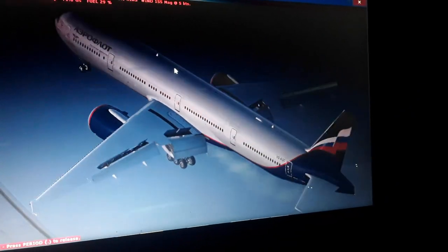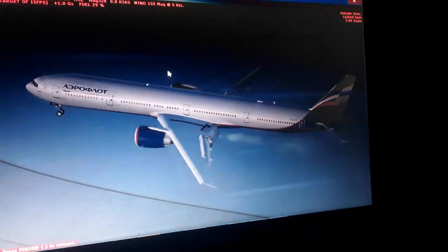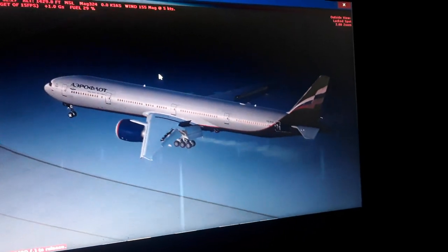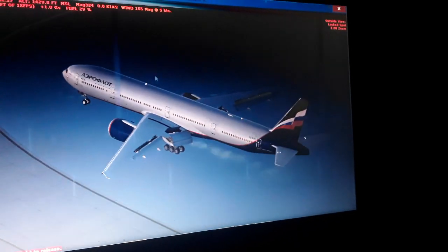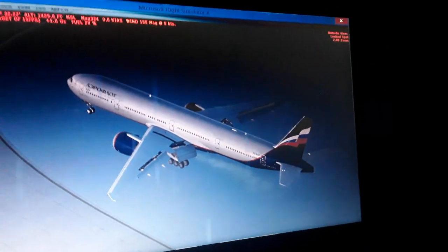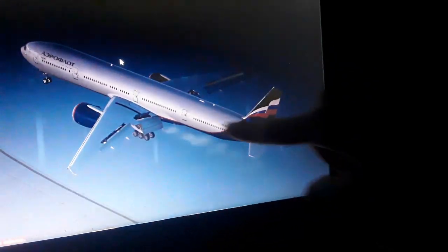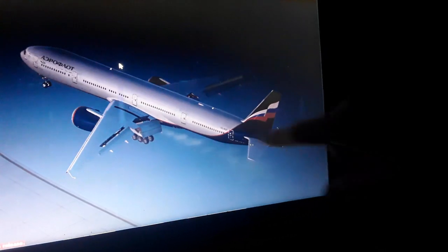Also you can see the vectors from the engines from the left and right forward propulsion. You can see also the lever, the center of gravity here, where the mean aerodynamic chord position is, this vector. Also the longitudinal vector from the nose to the tail, and the wingtip to wingtip vectors. And we have the center of gravity to the tail is the moment arm, or the lever arm position.